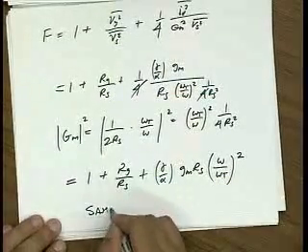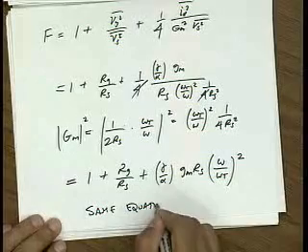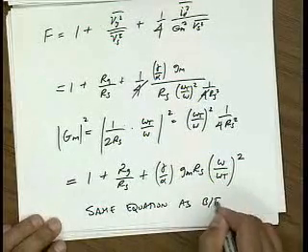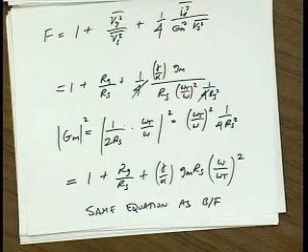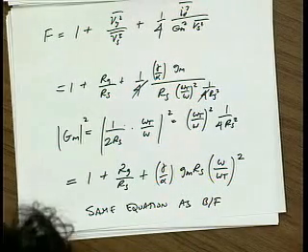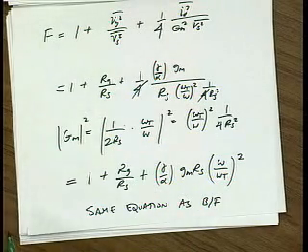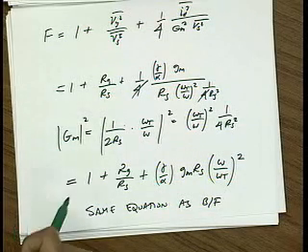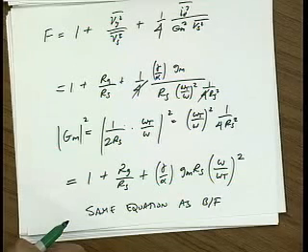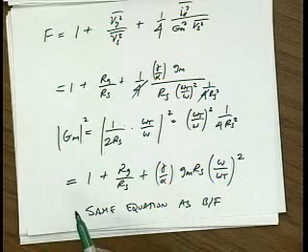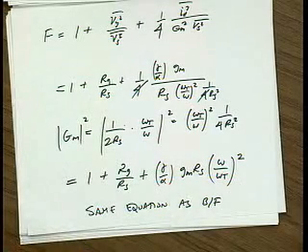So this is the same equation as before. In other words, we got lucky. The fact that we degenerated our device produced a real input impedance, which is very convenient for matching, and it didn't increase the noise. That means that the Fmin of the device is exactly the same as before. So to answer your question, we don't need to redo the calculations. It's all the same.